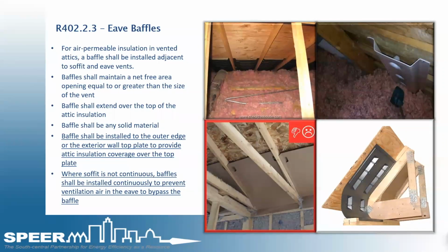So, just a little bit more about requirements. Protecting the insulation from wind washing is the eave baffle. Any air-permeable insulation in vented attics must have a baffle installed adjacent to the soffits.